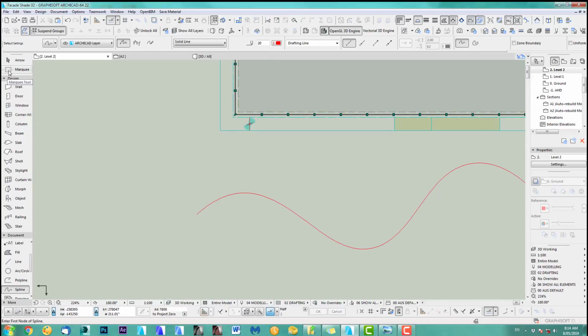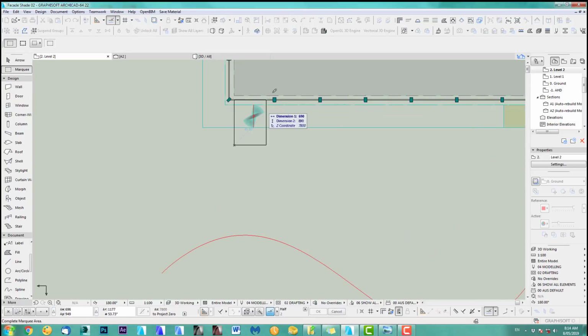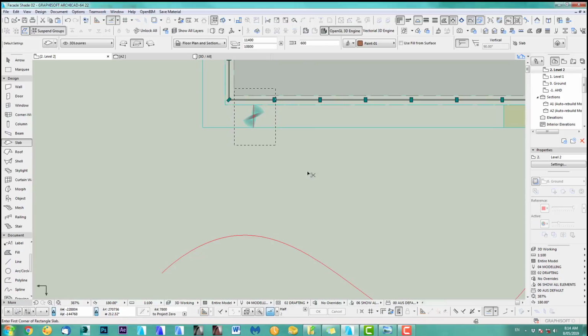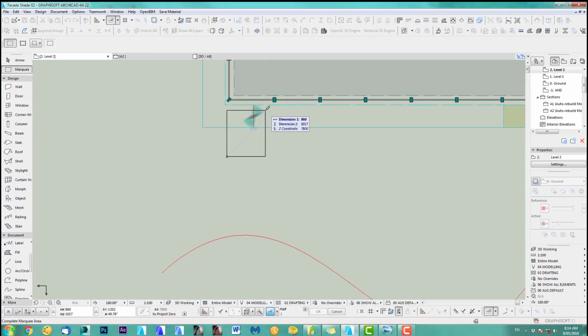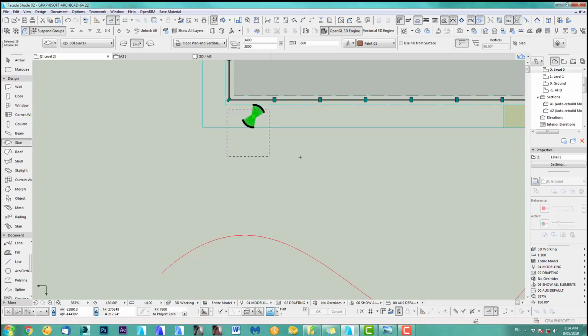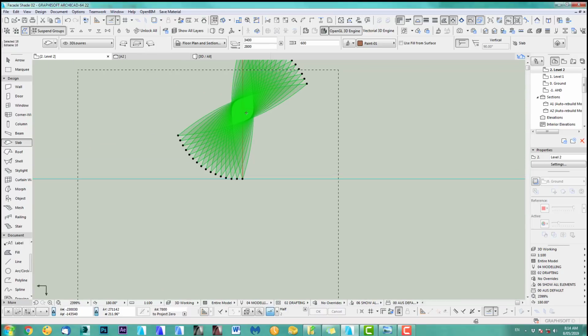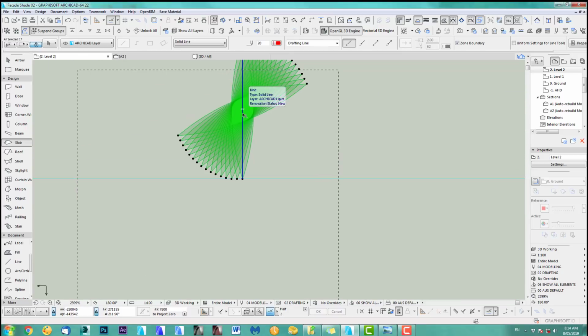So we go and take a frame, because I really only want to select this one. Hang on a second. Should have drawn the frame only right here, because I only want those slabs. So Marquee tool, slabs, select all. It will only take those. Now let's group those. Actually, you know what? Let's take one of the lines here.